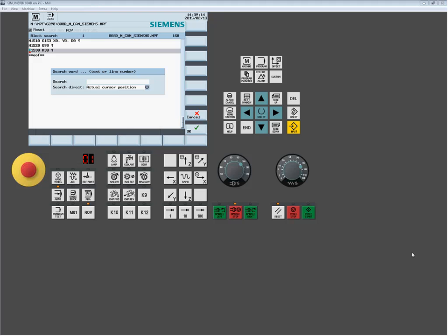So we load it up. Down here in the bottom, I'm doing my normal shutdown. Shut off my spindle, shut off my coolant. I'm canceling my tool, so I'm clearing my spindle. I'm disabling my tool offset. I do a quick tool change to actually clear the spindle. I use the super command again to stage my table at a safe point for loading, and I shut off my program.